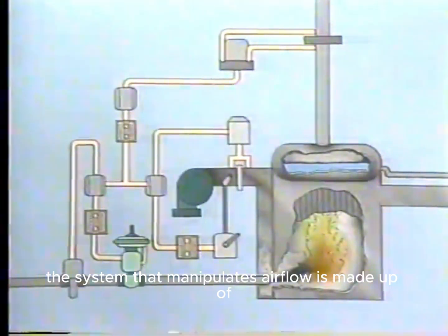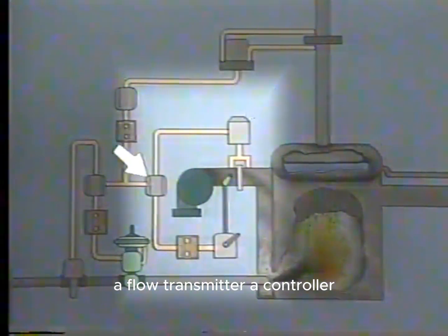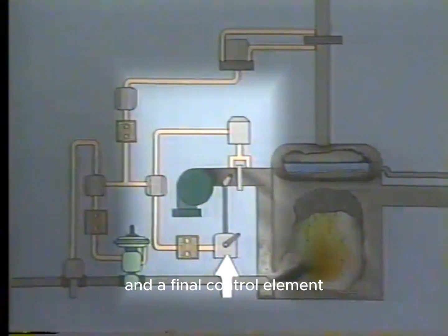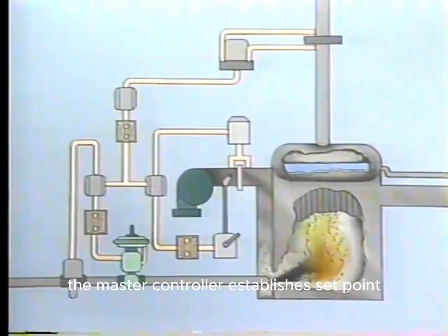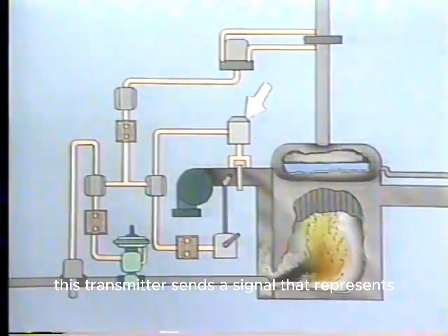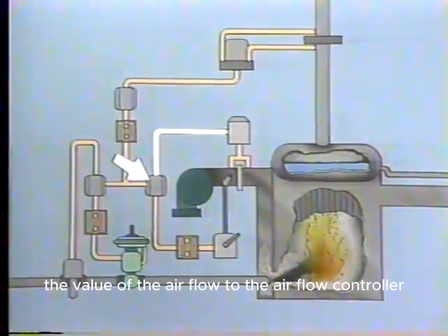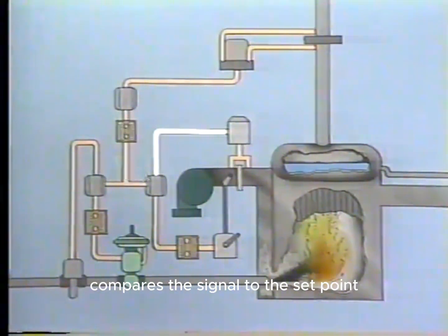The system that manipulates airflow is made up of a flow transmitter, a controller, a hand auto transfer station, and a final control element, which in this system is an actuator that operates louvers in an air duct. The master controller establishes set point for the airflow controller. This transmitter sends a signal that represents the value of the airflow to the airflow controller.